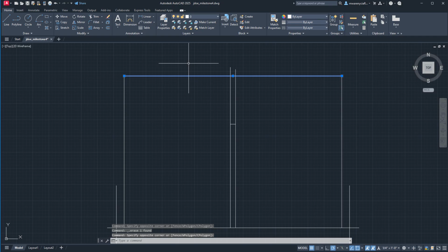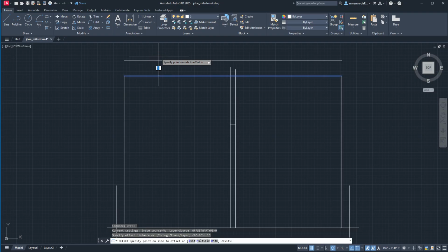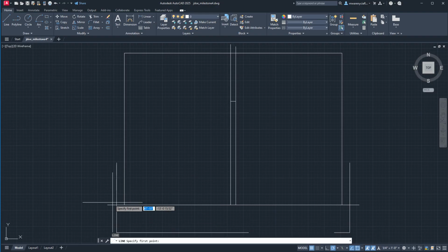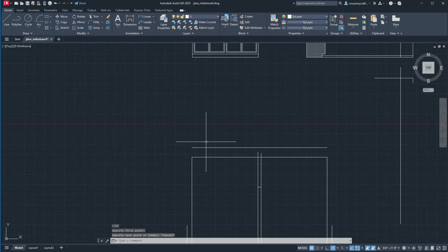I don't get into building like roofs or framing or construction pads really with you guys. We only have like today and tomorrow with AutoCAD. So we don't get crazy deep into structural stuff. So for the sake of this class, go ahead and use a 1 foot thickness for your roof. So we'll go ahead and do offset 1 foot. And then this wall should already be the 6 inches that we set right there when we did our initial offset over here. So I don't need to worry about that.